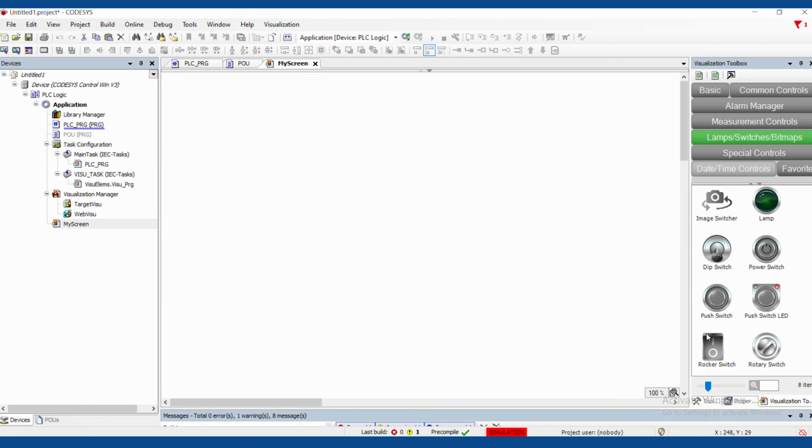It has things like typical lights and switches and push buttons and whatever. I personally try to stay away from all this 3D stuff in any kind of production environment because I find the graphics distracting. You want the operator to be able to see what's important, and if you've got all these details in 3D everything, I think it's harder for the operator to do that. That being said, I do tend to use these in my online demonstrations because they fit that format better.